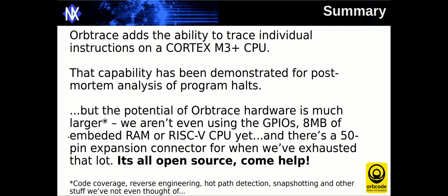Okay, so in summary, Orbtrace allows you the ability to trace individual instructions on anything Cortex-M3 and above. We've concentrated on M3 and above for now. A lot of the things that can be done with ITM, you can do other ways with interrupts and with program code. You can't do things using the ETM in the same way. It's simply not possible. So Orbtrace, as opposed to just straightforward orbtools using the ITM, gives you a novel capability you can't really get any other way.